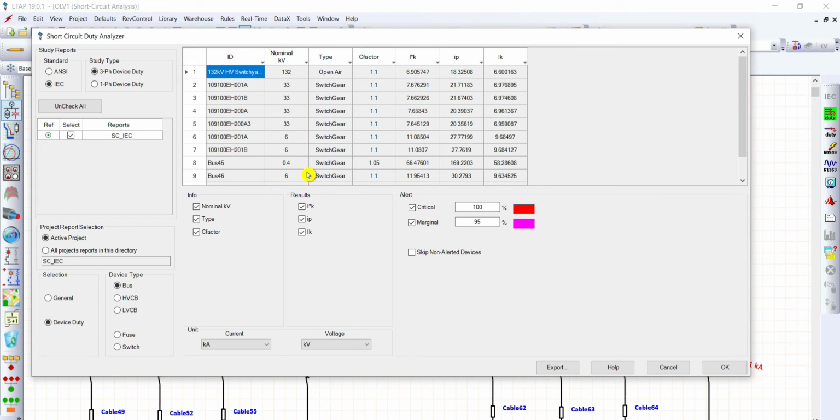For the low voltage switchgear, we have 66 kiloamperes. It's too huge, around 66.47 kiloamperes. The equivalent in the market right now is 85 kiloamperes, so we can propose the busbar rating to be 85 kiloamperes. Since we now know the initial symmetrical short circuit current and the peak short circuit current, we can provide this information and run the short circuit calculation simulation again.